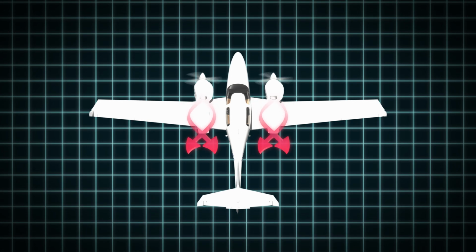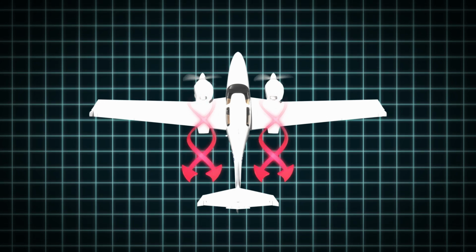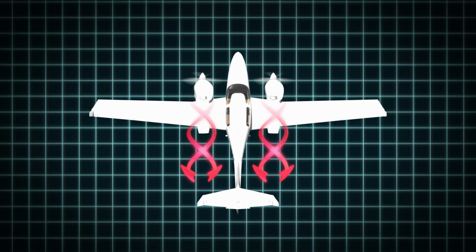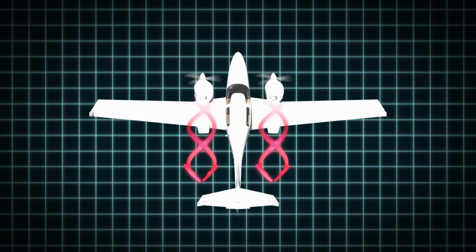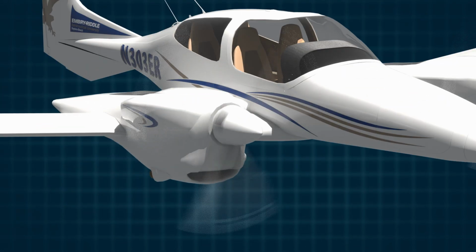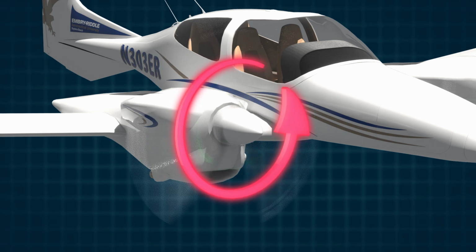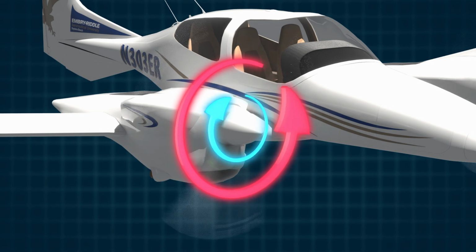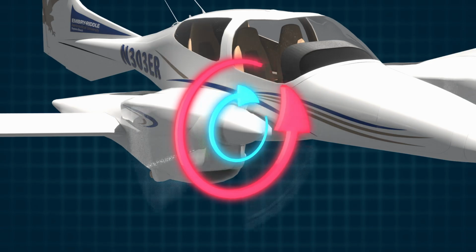This air pushed backwards is what is called prop wash. If a pilot increases thrust, the propeller bites more air, and as a result, pushes that air backwards. In simpler terms, a propeller creating more thrust creates more prop wash. Torque also plays a factor. Torque is based off of Newton's third law. Every action causes an equal but opposite reaction. As a propeller turns in one direction, there is an equal but opposite reaction in the opposite direction.